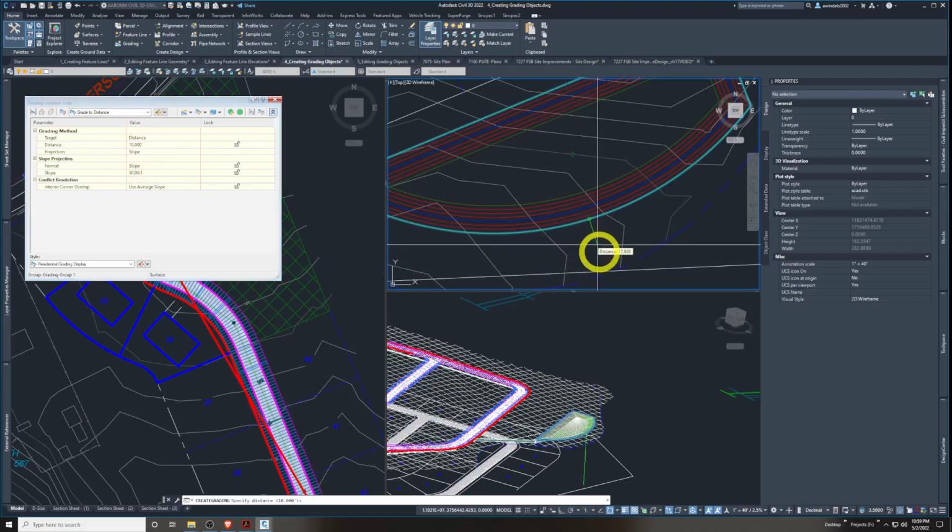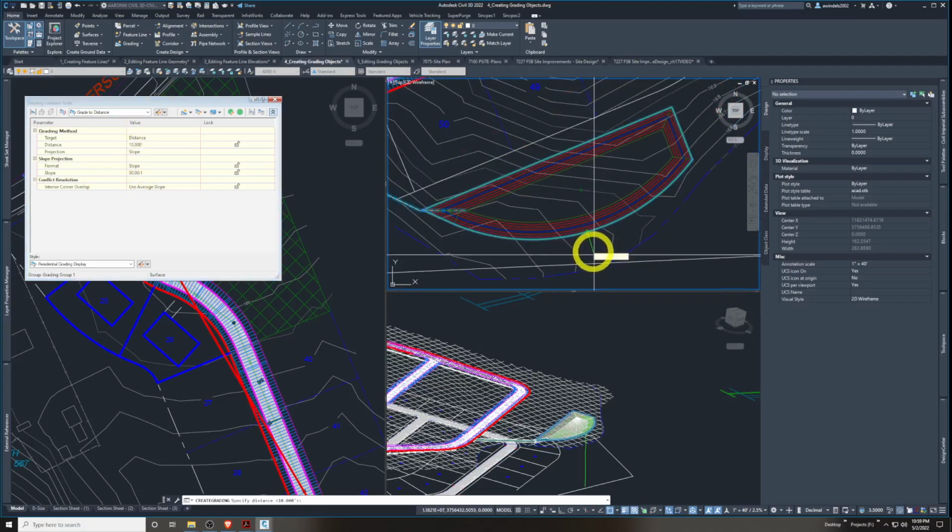And at this point, you can see a prompt coming up saying, well, I could also pick my distance here graphically. But in this case, I had the default distance at 10 in my criterion here. And it's also saying if I hit enter, it will accept that. And that's fine. That's what I want. I hit enter. And now it's going to the next option, the slope, as you see here. And also it's the next one cascading in this criterion.